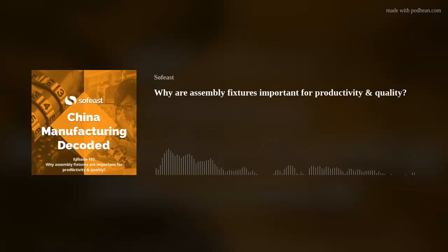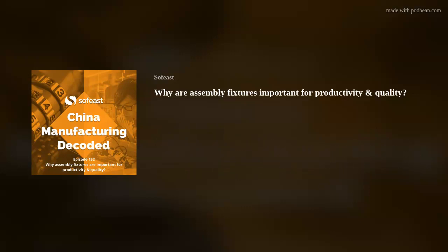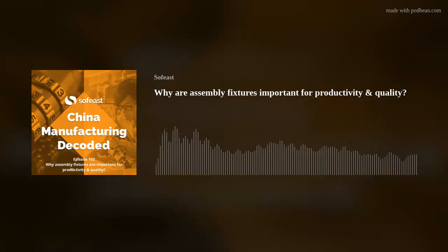Electromagnetic compatibility, yeah, that's right. If you've got static built up on your body, you're going to potentially fry one of these ICs. But how do you know that PCB has not already been picked up by somebody who's not wearing the protective equipment, and they've put their static electricity onto the component and fried the IC before you get a chance to put it into the assembly?